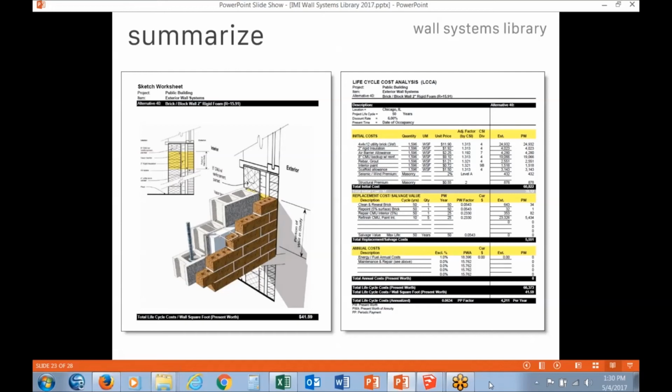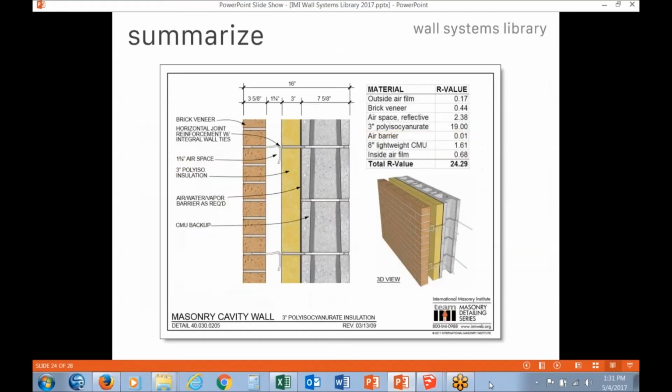Now, the problem with assigning cost data is that it's going to vary depending on the market you are in, the country. Labor scales vary widely, and material prices go up and down. So I think what we're going to probably start with is two things: fire resistance ratings and R values. Back in that index, you can build your wall. When the PDF gets pushed to you of the wall that you built, you can see how many hours of fire resistance that wall has, and what the R value is.